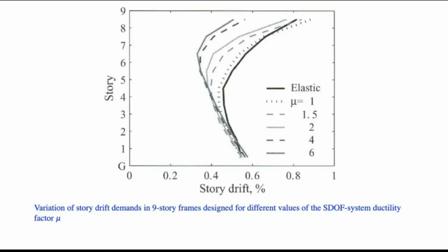when the structure is elastic, all the energy is distributed along the height of the structure. So every floor is contributing and is almost equally subjected to the seismic excitation. But what happens is that when yielding happens in a given story at a given plastic hinge, all the energy is concentrated at those points, because there is a flexibility that is produced there as the stiffness drops. So all the deformation is concentrated at those points. So the deformation increases at that point. The upper stories are then subjected to relatively less energy and less deformation demands.